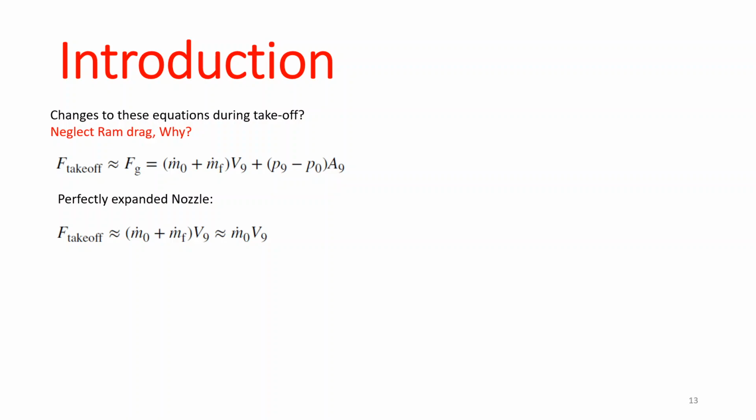So for the air mass flow rate, you just put a pitot tube there and calculate. That's it. The exit velocity is, of course, a little more complicated, but you have to have a flow meter at the exit, right, to be able to calculate it. Okay.